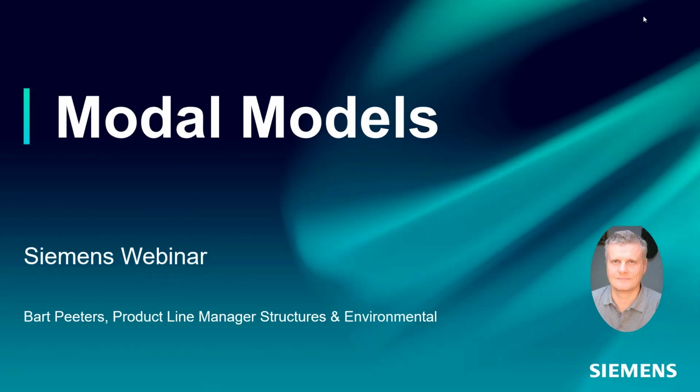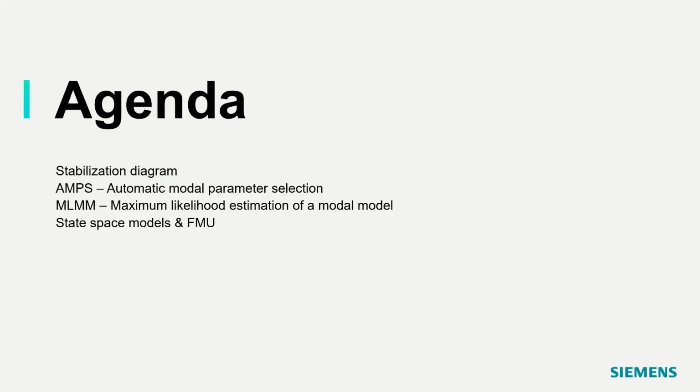Yeah, thanks a lot for the introduction. The next hour, I will try to cover the following topics. We will discuss stabilization diagrams, quite important in the modal analysis process. Then we look a bit into the background of automatic modal parameter selection, a tool that makes modal analysis quite user-friendly. We have a relatively new method also that I want to discuss, the so-called MLMM method, which stands for maximum likelihood estimation of a modal model.